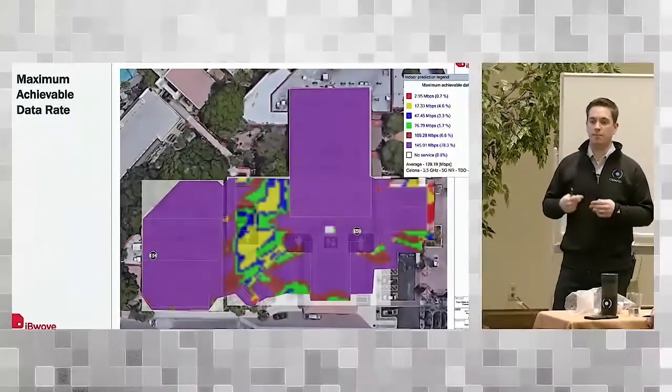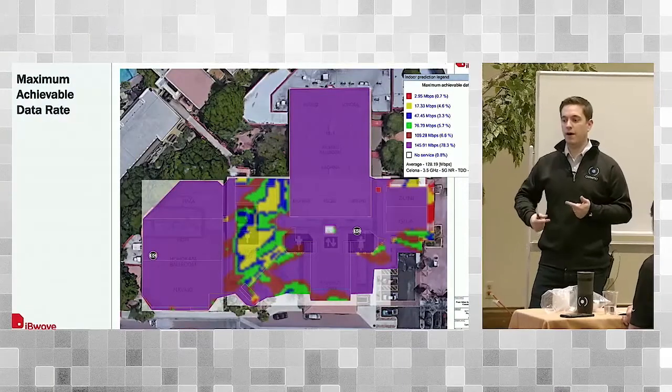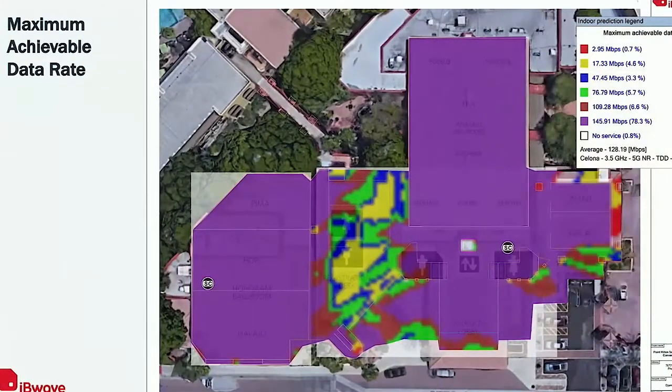The other interesting thing about LTE from a planning and design perspective is that there are very well-defined SINR to MCS or data rate mappings for LTE. These are tested, certified and validated before a carrier will put them on their macro network. So at this SINR, you need to achieve this performance level, and every client device is validated before carriers will put it on their network.